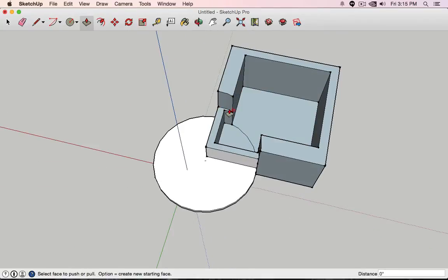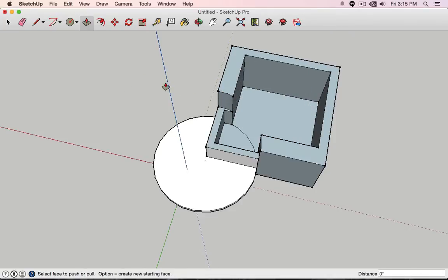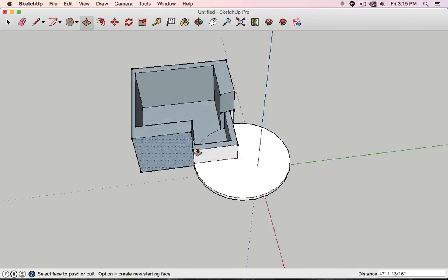So those arced parts actually right now prevent me from pushing this face back to make it thin, for example, like here. But that's okay. What I did here was kind of making a really messy mesh. That's not what we want anyway. So let's take a look at how we draw a good and correct floor plan with the offset tool.